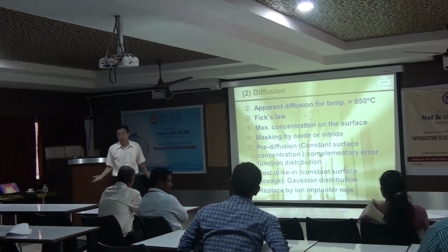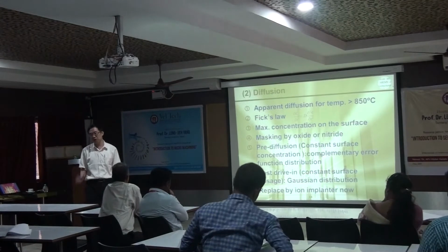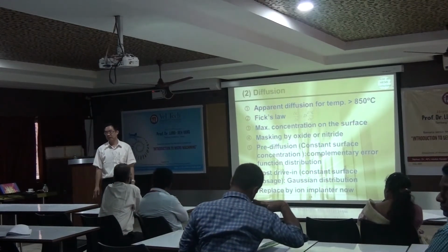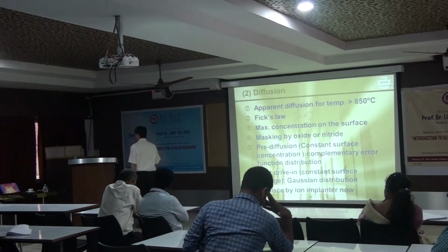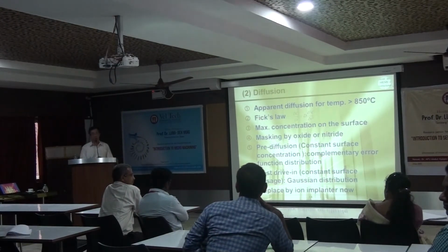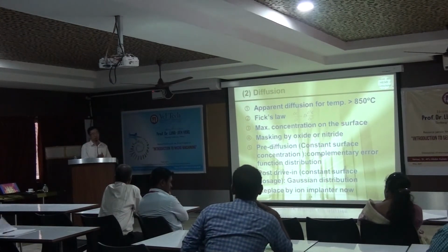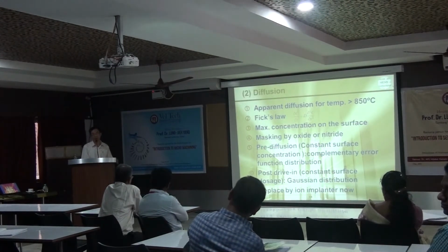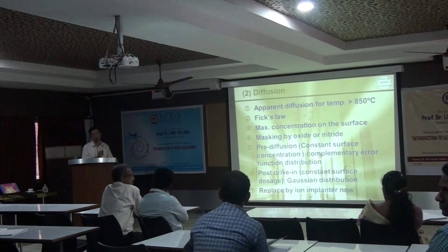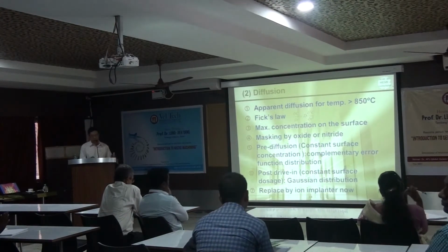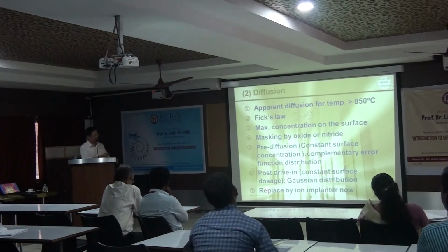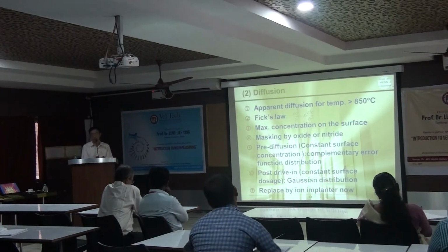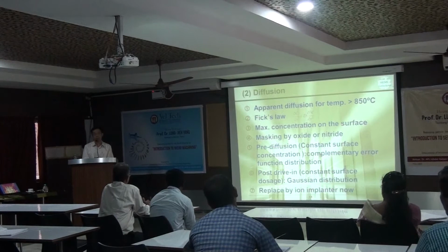But impossible, right? Because diffusion is a natural phenomenon. You cannot prevent it. So diffusion is no use for the sub-micron device or nano device. Impossible. So we change to use the ion implantation method. Ion implantation.